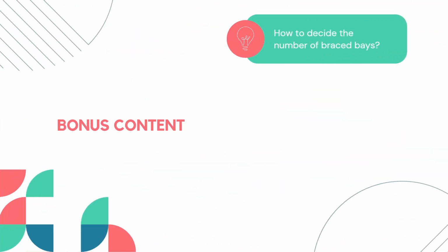Before moving on to the third part of the video, there is bonus information regarding how to decide the number of brace bays, their position, and so on. So, how to decide the number of brace bays? As per IS 800 clause 3.10.3.2, the maximum spacing between two braced bay centers should be restricted to 50 meter. So, if you have a building of length 80 meter, then we might require 3 braced bays.